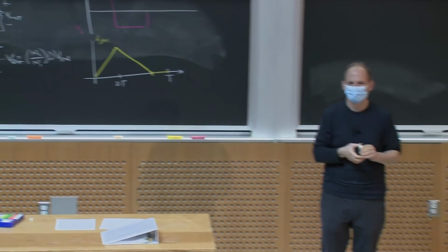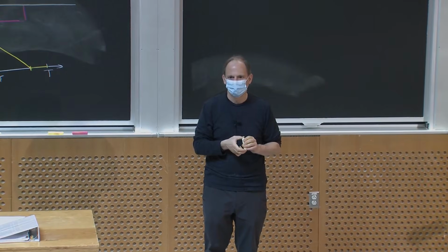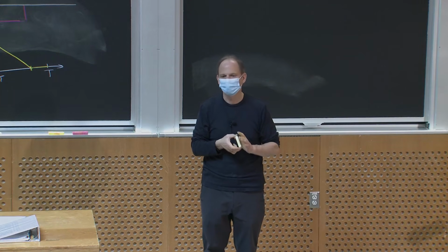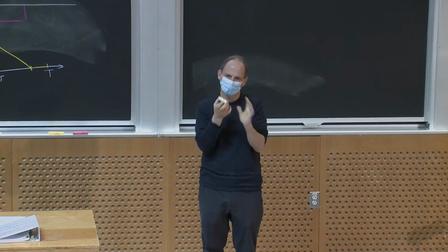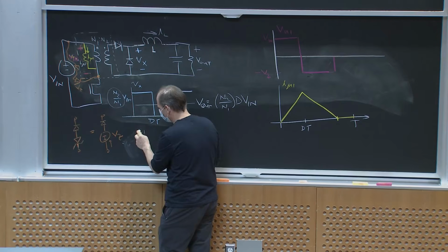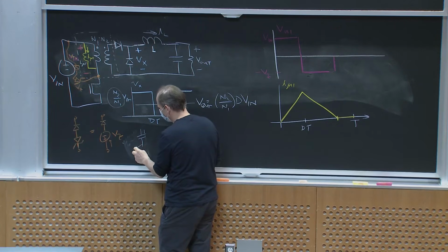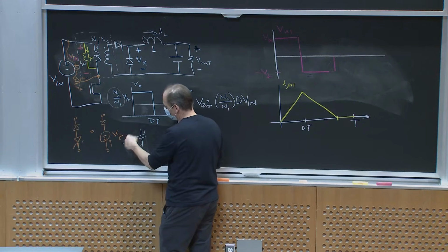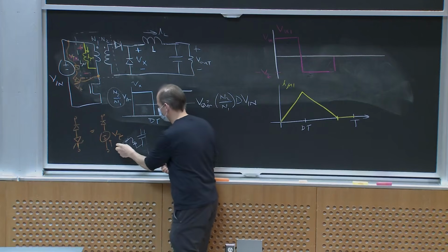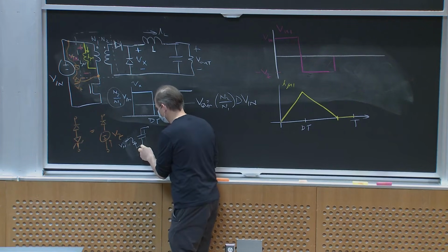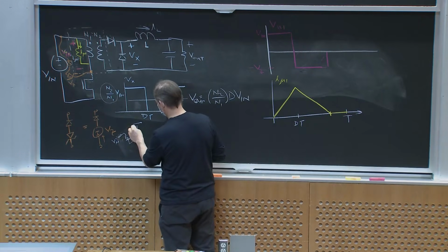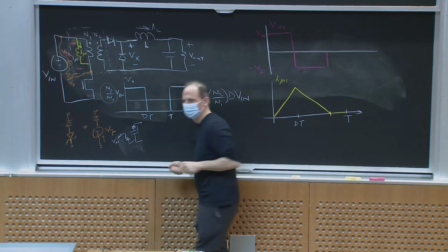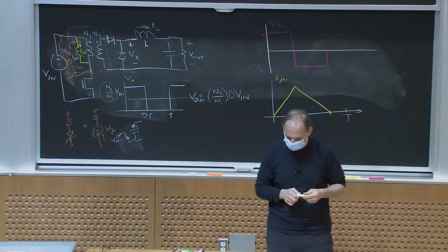Yeah. So in this case, is the Zener diode just acting like a sink, like a resistor? It's just acting like a resistor, except that it's a fixed voltage. It clamps it. And you could replace that with a capacitor and then bleed that capacitor back down to some average value like Vn. Right? So you could have connected it like this too. Okay? You would have still needed a diode there.